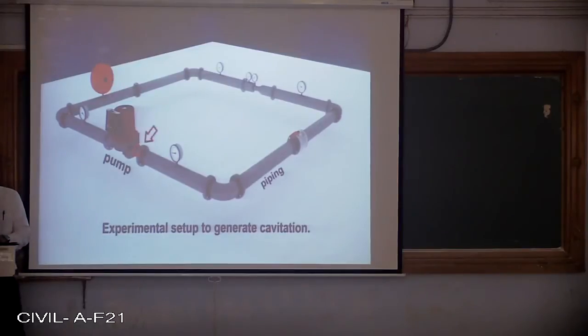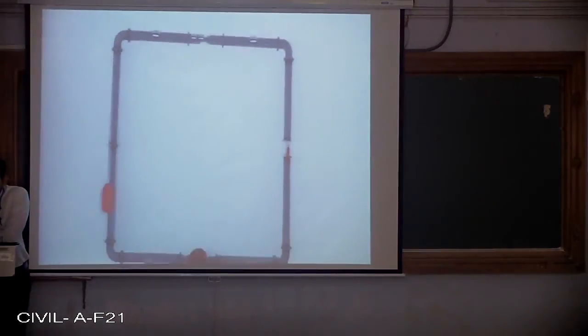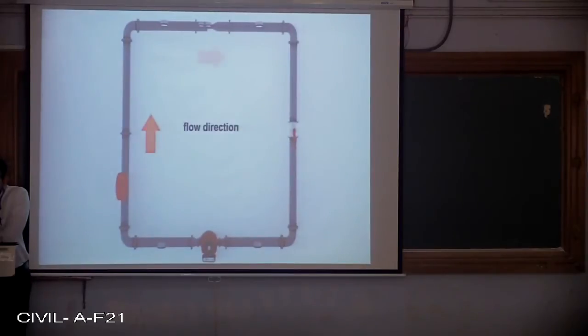At the inlet of pumps and in narrow pipe sections: if the pressure at the inlet of a pump is low and approaches the vapor pressure, cavitation can occur at the pump impeller, as we have seen with the ship propeller. The pump can deliver less water because the cavitation bubbles occupy a part of the cross-section where the water should flow. Damage from collapsing vapor bubbles will be shown later.